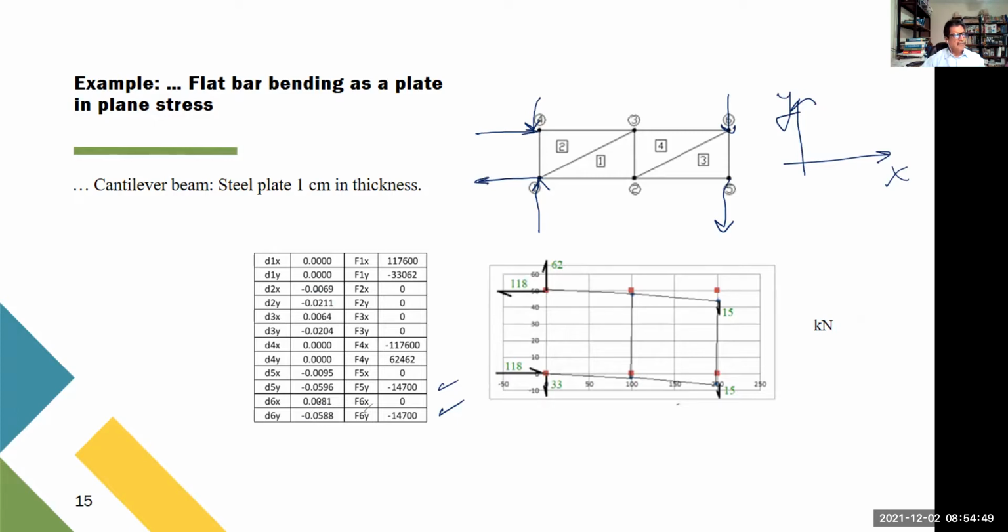You see this moves to the right and moves downward. But you see that to the right it moves 2 zeros, 1 8. Downwards it moves 1 0, 6. So this is basically 10 times that, much larger. So in the x direction, basically there is not much. In the y direction, there is a large deflection. That's something that we have assumed. Okay.